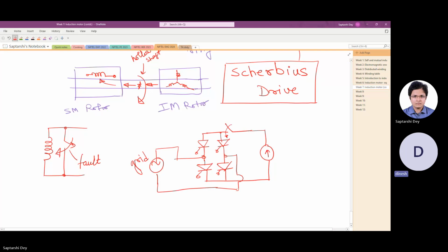You can try paralleling a resistor across this inductor, the current source, and then the IR voltage I can feed back to this circuit. You said you have an inductor through which some current was flowing. So this is equivalent to this current source, and the current will keep decreasing. But nature-wise, what is an inductor? An inductor is something that stops any sudden change of current through it.